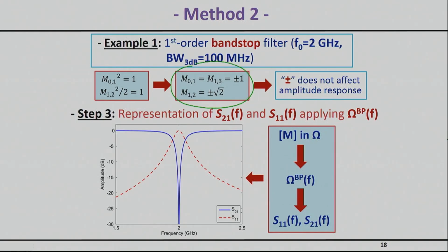So this is the coupling from, for example, the source to the non-resonating node, and so on and so forth. And that actually gives you the exact response you want. The last thing that is left is to basically utilize the bandpass frequency mapping that we covered before, and it will basically shift your entire frequency response, which is shown here, to the desired domain. So it will shift basically to a resonance of 2 gigahertz.